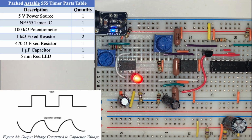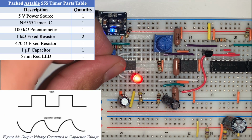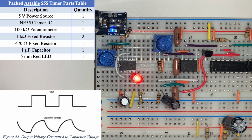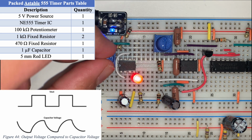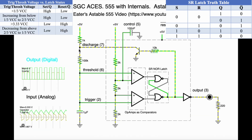In astable mode, the 555 timer acts as a free-running oscillator, continuously switching its output between high and low. This creates a square wave signal that blinks an LED. The frequency of oscillation is determined by the timing components R1, R2, and C1. C1 charges through R1 and R2.